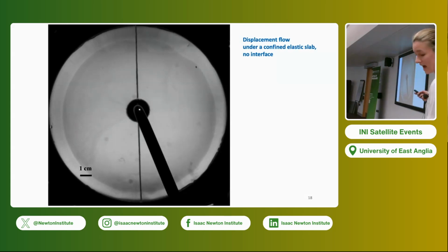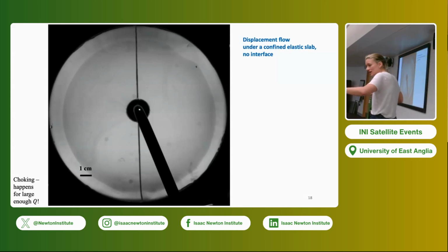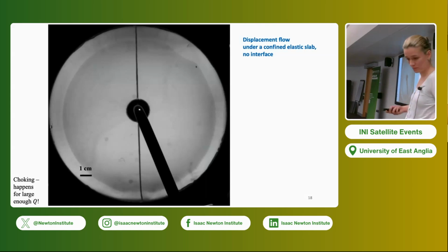I should point out that that happens at sufficiently high injection rates. And of course, in this experiment, we're controlling the injection rate. So in order to actually observe trapping, the actual physical mechanism is you inject at the constant injection rate, but then when the choking event happens, the pressure inside your system increases enormously, and that stalls your injection, your syringe pump that actually pumps in the liquid at the constant rate. So that's actually what happens in practice, how the stalling happens.